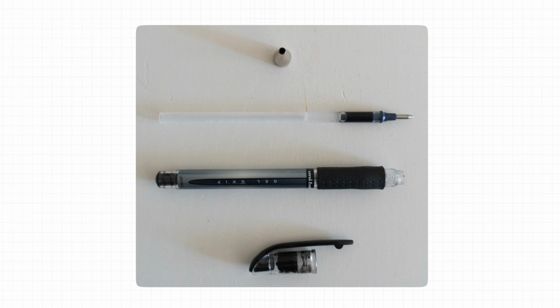And one thing that I'd just like to say before you start going out and creating your own 3D models, before you even open up Fusion, it's a really good idea to start thinking about the way the design's going to go together. So this pen, for example, first I'll break it down into its individual components. And then I'd look at each element to understand what tool would work best for each part. Perhaps one section would work best as a revolve, but others may be better as an extrude, or maybe even a sweep. I'd understand how I'm roughly going to create the design first, and then open up Fusion.